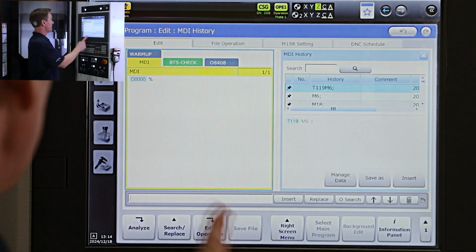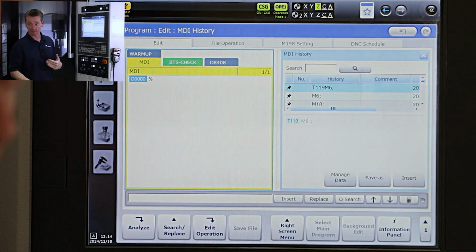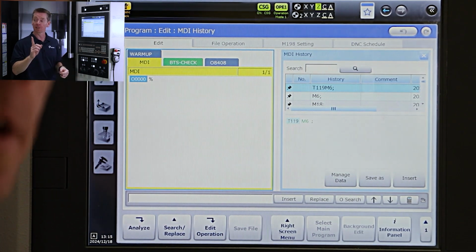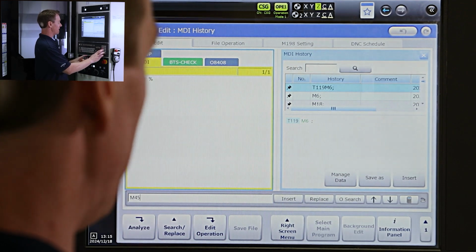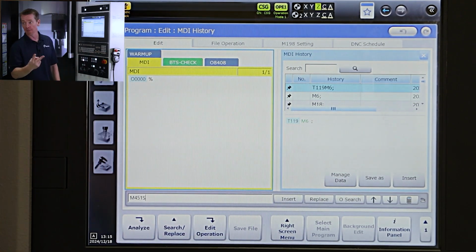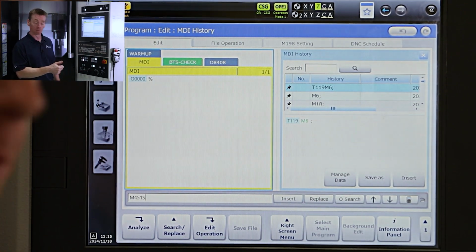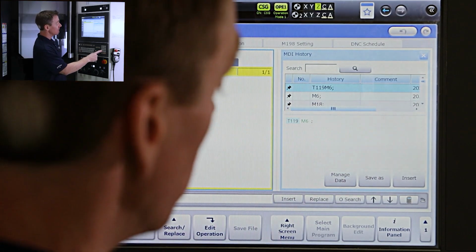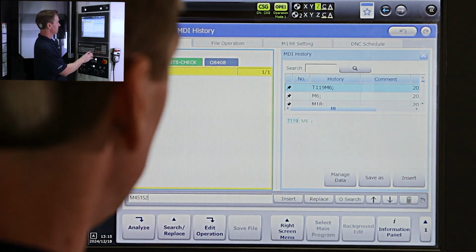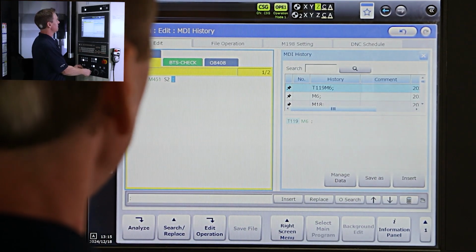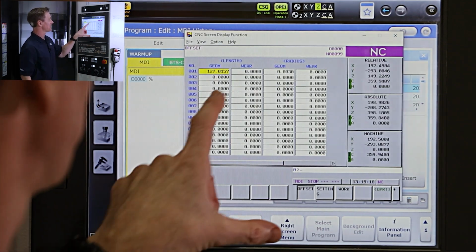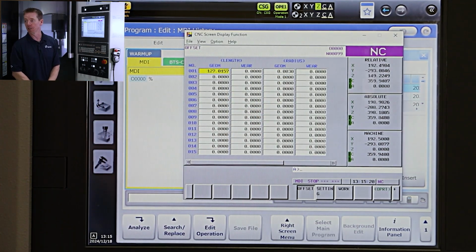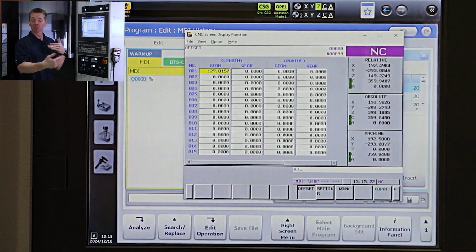Okay. Now, if I want to activate the second offset, the first offset is always active on a tool change by default. I will do an M451, an S, and then the cutter number. We have 2 of them on this tool, so it has to be a 1 or a 2. I'm going to make it a 2. And if we execute this, and we go back to our FANUC side of the screen, you're going to notice there's that 3 micron change. Okay? So we can switch in between.